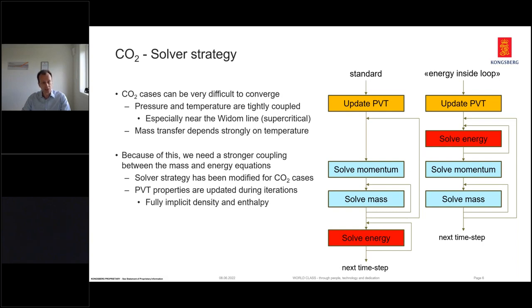That means even in single phase supercritical conditions, it can be very difficult to solve this, even if there's no phase transition. The reason is that, for instance, the density can change over the course of a few degrees Celsius, around, let's say, 50%, if you go from liquid-like to gas-like supercritical fluid.